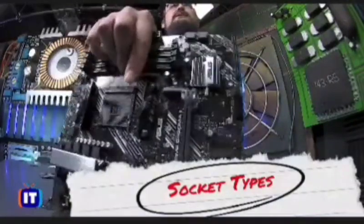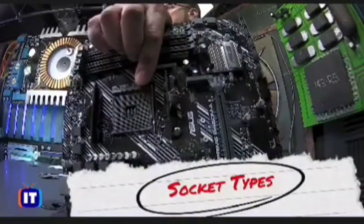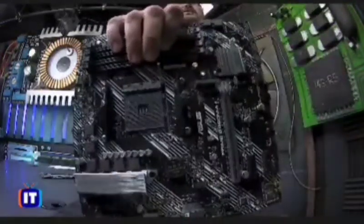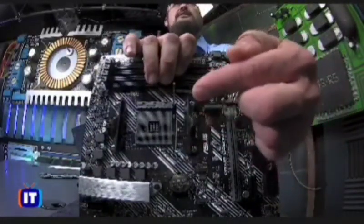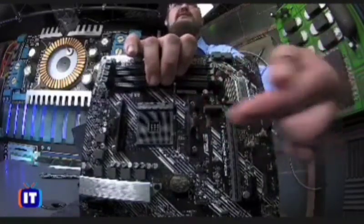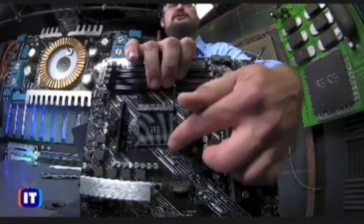This right here is what is known as a PGA-based socket. This is what's called pin grid array. More specifically, if you've never heard of this socket type, this is what's known as a ZIF socket, a zero insertion force socket. In the early days of computing, they realized that with these CPUs getting so hot, cooling down, heating up, cooling down, they could literally walk themselves right out of their own sockets through expansion and contraction, something known as chip creep.